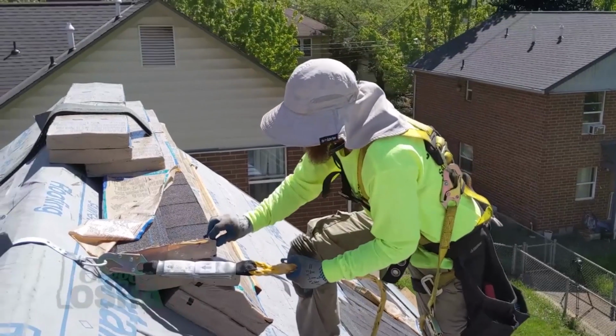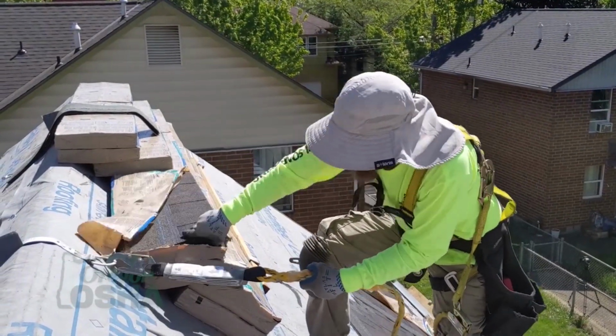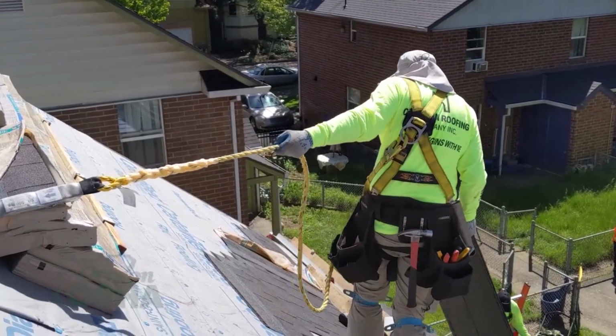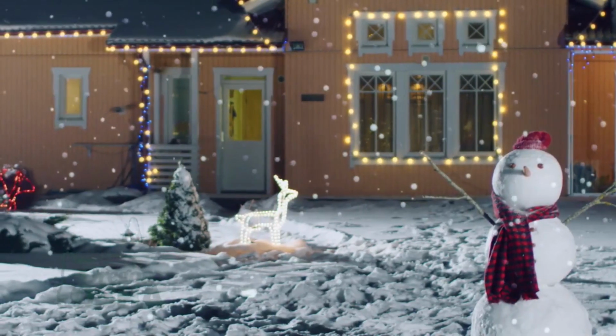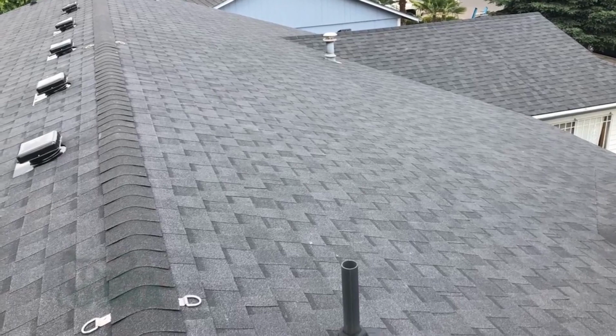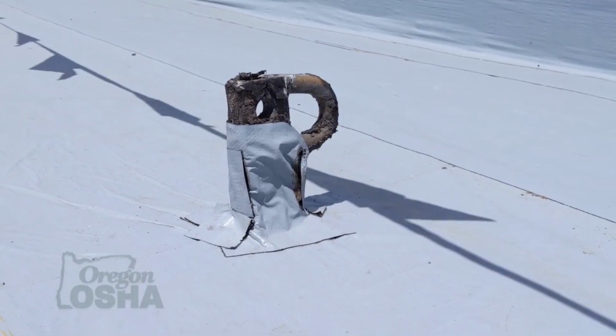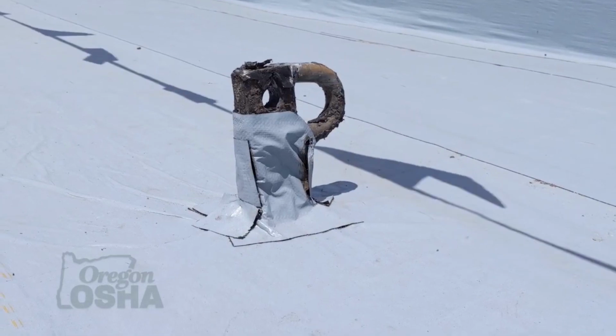I think any new residential house should have the roofer automatically put in what we call ridge 1s and ridge 2s. They're just an anchor that goes up at the ridge, strapped with stainless steel strap. And then there's a little tiny D-ring on each side. So if you've got somebody that's going to go up there and do your Christmas lights, clean your gutters, they have somewhere to anchor off to. The other thing is, for a lot of the new commercial buildings, we're putting in permanent roof anchor systems. And bam, put it up there, there's always somewhere to tie off.